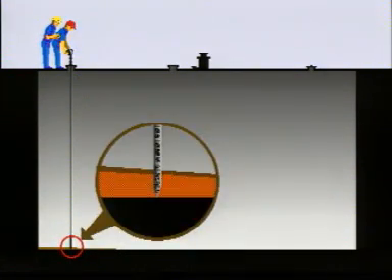When the cargo is discharged, all tanks will be searched for remaining cargo on board, ROB. The tanks will be dipped only in the aft part. The special sounding rod fitted to the MMC is used. Too often there is discussion of ROB even when the indication on the sounding rod is less than an inch or a few centimetres.